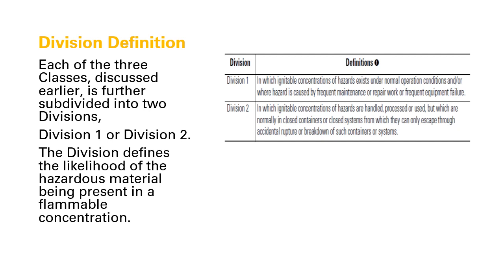So this type of zone is known as Division 1. And what is Division 2? Division 2 is where under normal condition there is no hazard, but in abnormal condition, which may occur due to the rupture of equipment or any container leakage like this. So in this way we categorize Division 1 and Division 2.